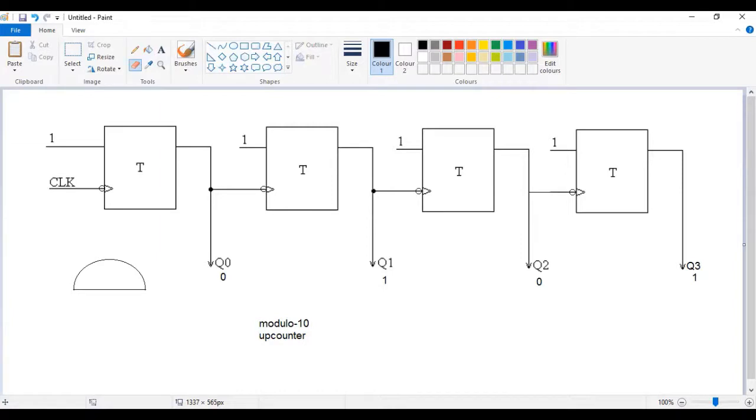Now the output of your AND gate is going to be high when all the inputs are high. So if you want to connect this one, for example, to your AND gate, basically you're connecting all the states there. Since this one is already low, you're going to negate it so that it becomes high. So this one would have a small node next to it, which means you're negating it.